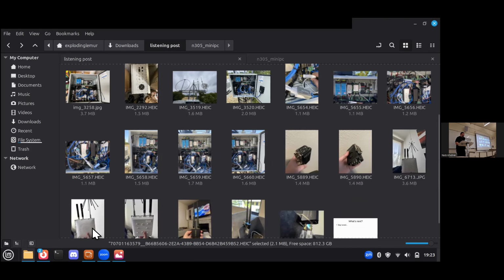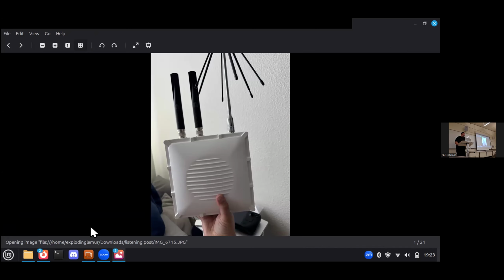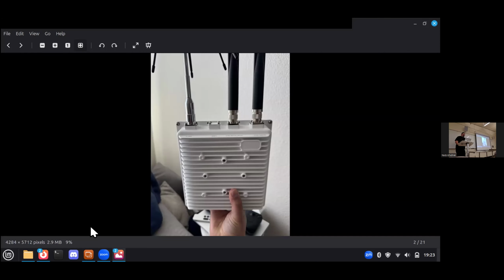Yeah, so for this particular thing, since it's a sealed box, there's no air exchange with the outside environment, and so it would just heat up and heat up. Air is not a great conductor of heat, so using air to conduct heat from a hot processor to a different heat sink that is then trying to conduct that heat away to air, it's just going to get really hot in there and not be as effective as if I couple it directly to the case.